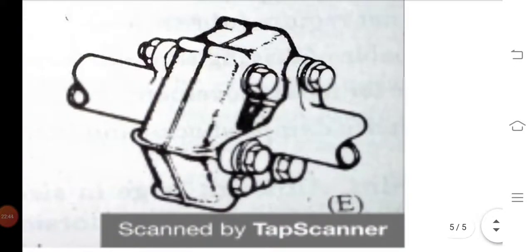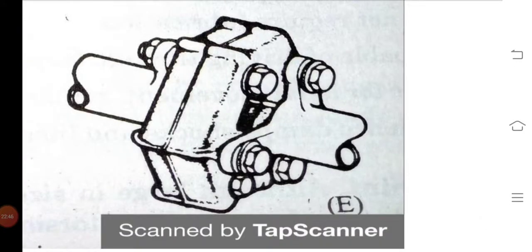This is the donut type, and the size of this universal joint is quite large. The great flexibility of this joint provides a soft cushioning effect on the driveline, and it absorbs the majority of torsional shocks generated by the action of other joints or by vibration from either the engine or road wheels.